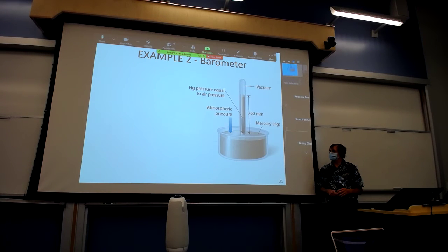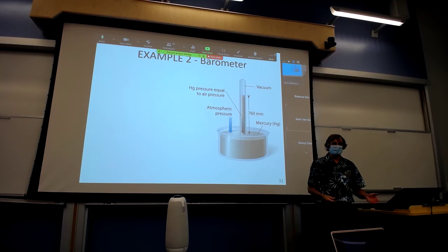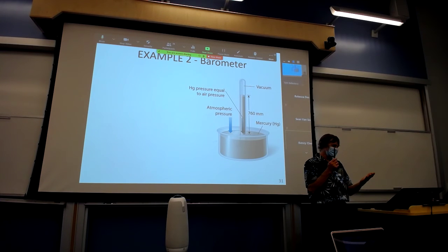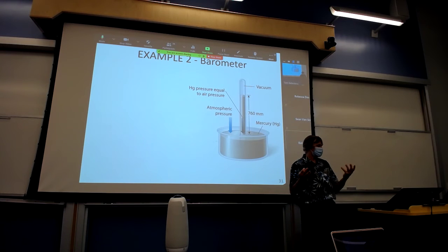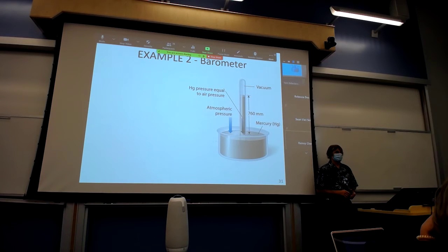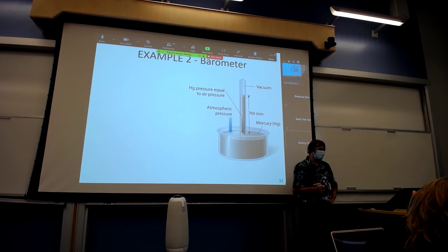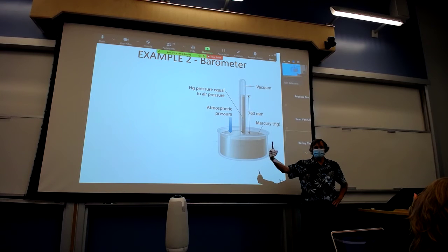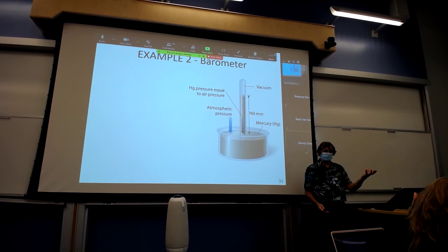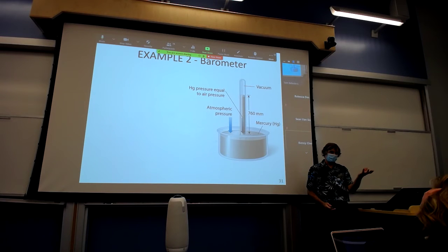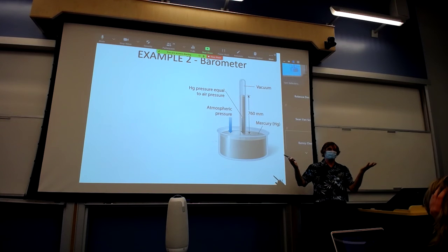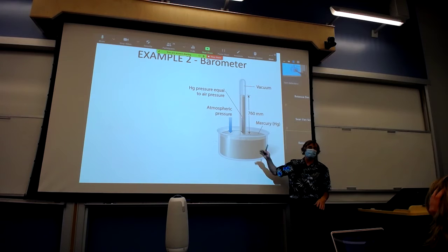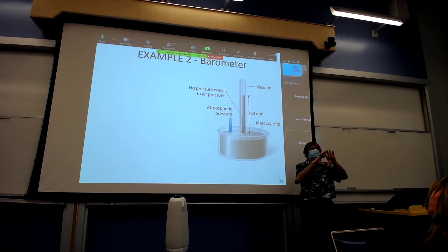Okay, here's the second example for today. Many of you, if you ever listen to the weather on either the television or on the radio, they'll talk about barometric pressure. So remember, when we talked about pressure measurement, we indicated that there are certain devices that measure absolute pressure in the absolute pressure measurement datum, and other gauges that only measure gauge or local pressure. And the difference is that anything that measures gauge pressure, that gauge is zeroed on local atmospheric pressure.